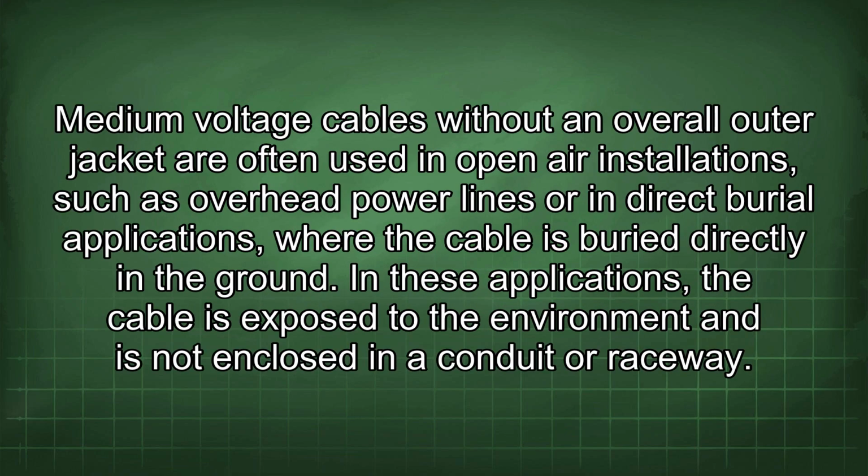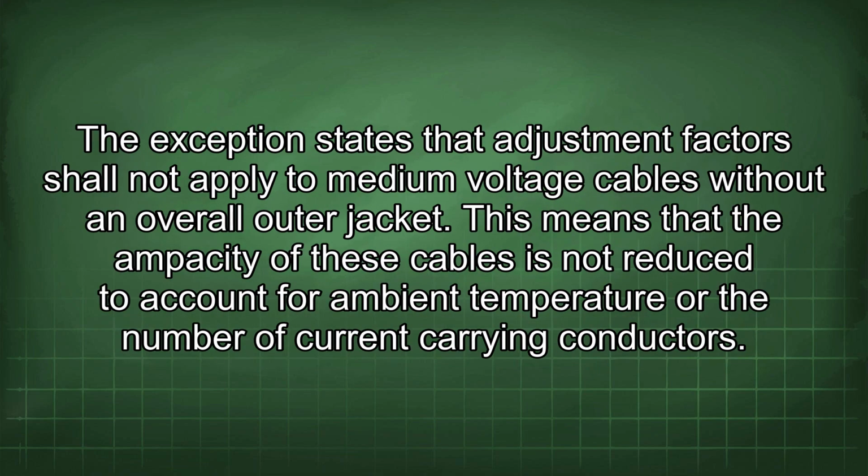Medium voltage cables without an overall outer jacket are often used in open-air installations, such as overhead power lines or in direct burial applications, where the cable is buried directly in the ground. In these applications, the cable is exposed to the environment and is not enclosed in a conduit or raceway. The exception states that adjustment factors shall not apply to medium voltage cables without an overall outer jacket. This means that the ampacity of these cables is not reduced to account for ambient temperature or the number of